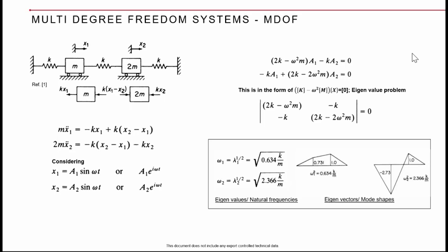So for example, you take any simply supported beam, the first mode will look like this, something like that. In the second mode, you will see something like that. In the third mode, you will have another symmetric mode, and then the fourth mode, you will have again an antisymmetric mode. So understanding these mode shapes will help you to guess which mode is more severe to you before the analysis itself, I mean, before doing the detailed analysis itself.